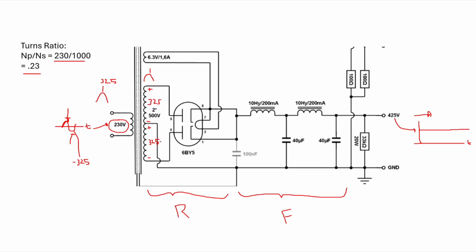This is a center tap, and this center tap comes down and it forms our ground. So everything is referenced to that. Okay, let me draw ground here. If you're above ground, you're positive relative to ground. If you're below ground in voltage, you're negative relative to ground. So we've established our ground as the center tap. So when we're at this peak point right here, we have a positive relative to the center tap of 3.